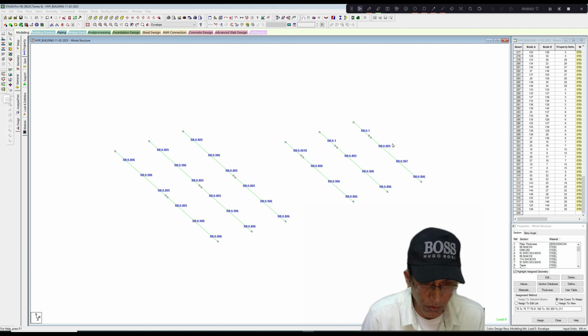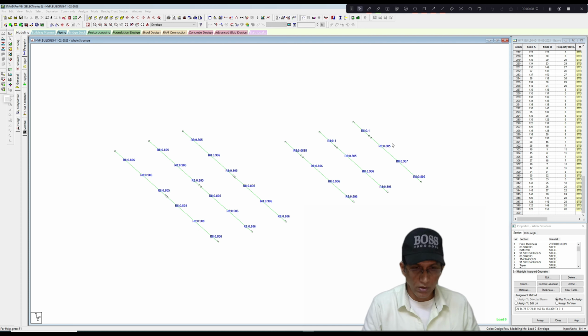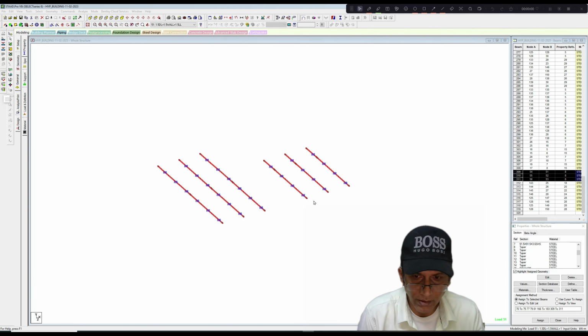When the interaction ratio of a simply supported beam reaches or exceeds 0.75, we should definitely check the vertical deflection with respect to serviceability. Usually, if the interaction ratios remain below 0.75, the joist or simply supported beam satisfies the deflection limit of span by 240. IS 800-2007 gives deflection limits with respect to live load only, and it doesn't define any deflection limit with respect to dead load plus live load.